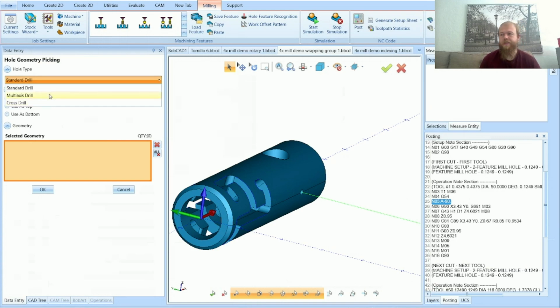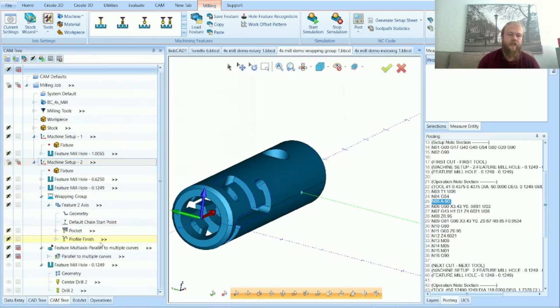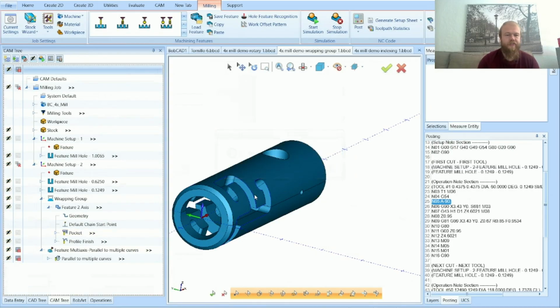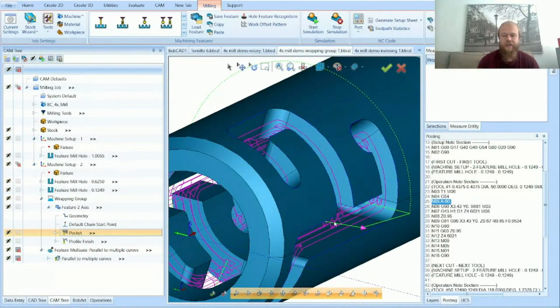That would be for 5-axis machining if you need to index in 5-axis. So just one way to save you time without having to index for drilling operations there. Makes things nice and easy. Next, we'll take a look at doing the profile finish inside of these areas here.